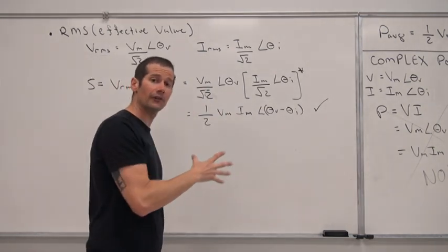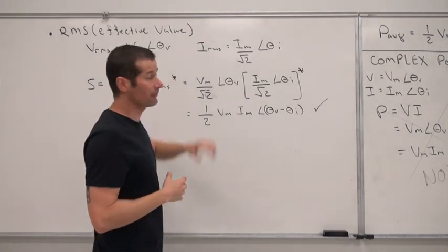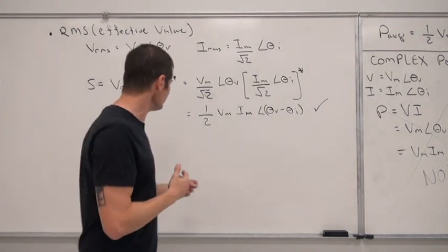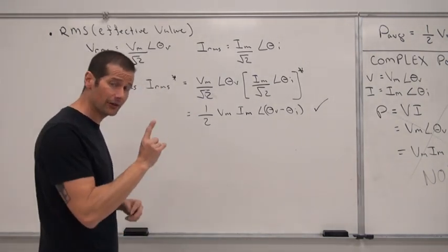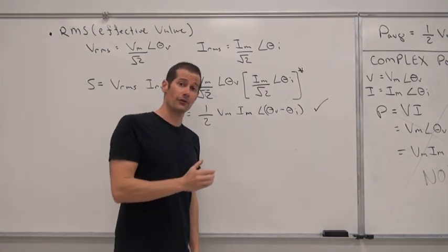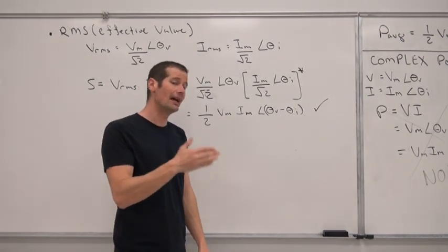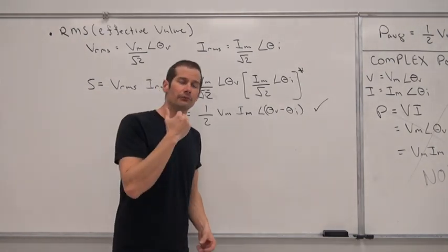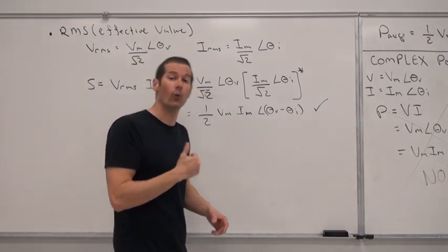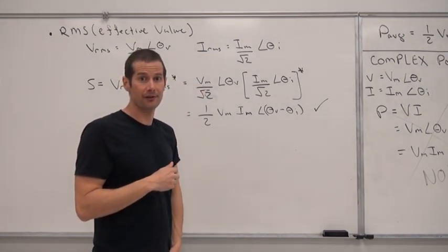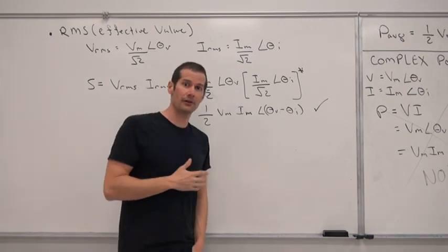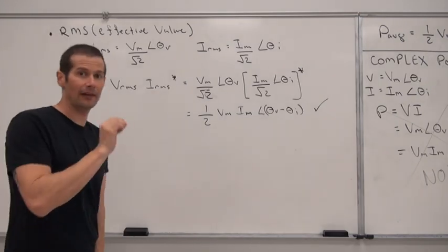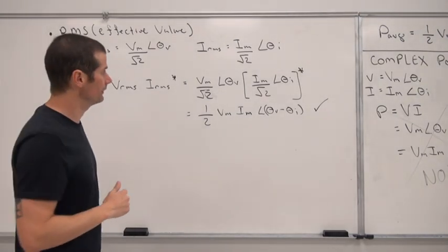So the RMS values do produce the exact same thing, but the reason we utilize RMS values is to make our calculations a little bit simpler. If we start off in our calculations with an RMS voltage source or an RMS current source, that means every single current or voltage within that circuit is going to have that effective value, or will be in terms of RMS. The way we can always ensure our calculations are correct is by ensuring that it is denoted up front within the calculation.